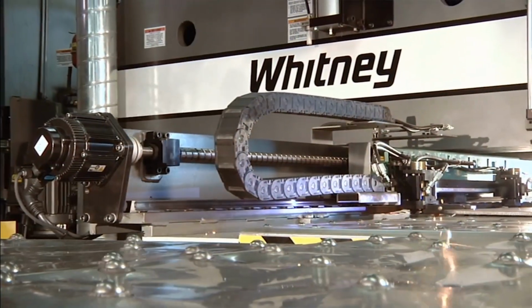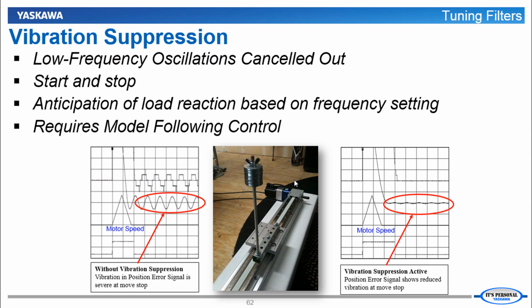So it is a real problem, and it can be advantageous for compact machine design or some other design constraint that the actuator must be located somewhat at a distance from the actual workpiece. So if the machine designer is able to confidently make this type of machine, knowing that vibration will not be an issue, it can remove a lot of those design constraints and result in better performing machines.